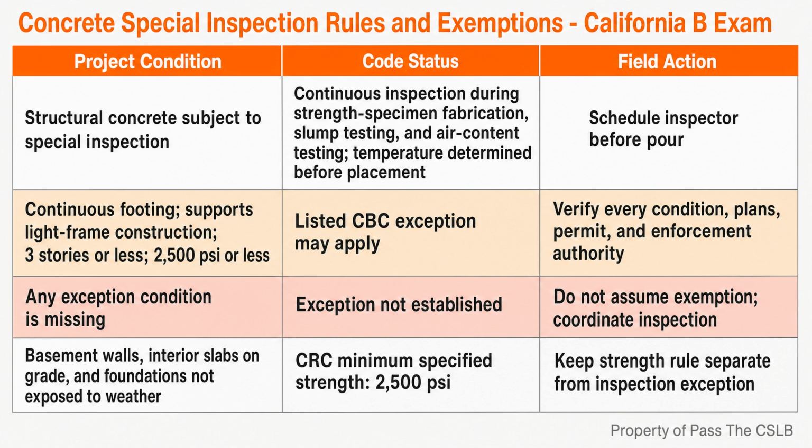I also watch the placement plan itself. Poor access, delayed trucks, congested reinforcing steel, or inadequate labor can create pressure to change the concrete. Those are coordination problems. I do not solve a coordination problem by silently changing the material. Before concrete starts moving, the forms, falsework, access, reinforcing steel protection, testing personnel, and placement crew must be ready. Once wet concrete is in motion, every unresolved issue becomes harder and more expensive to correct.